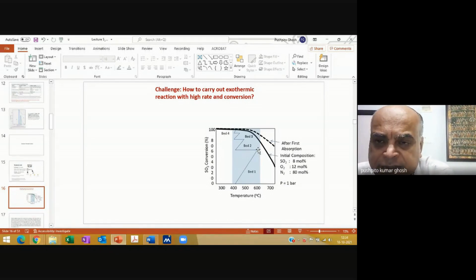I can take my catalyst bed, the height, diameter, etc., so that I decide the amount of catalyst to amount of substrate, etc. The other is I can vary the flow rate of my substrate through the catalyst. So if I see that the temperature is rising, I can just make it go a bit faster. Obviously I can't take out catalyst suddenly, but I might be able to play with it.